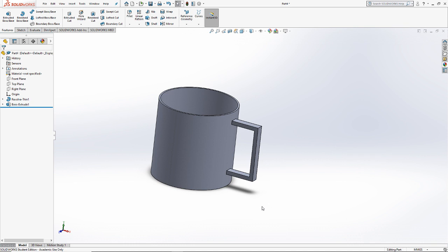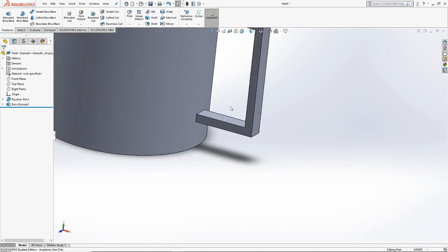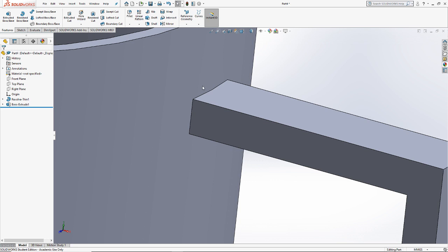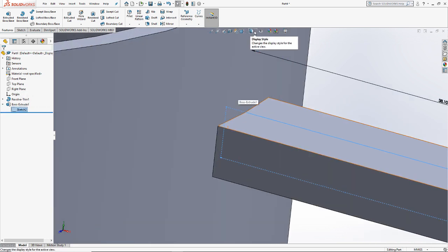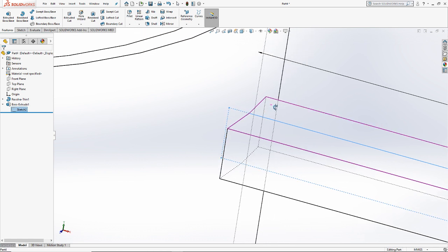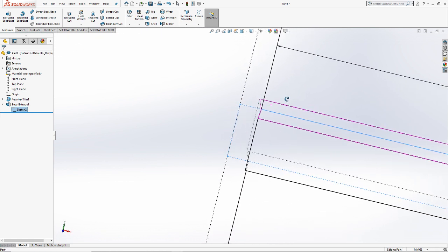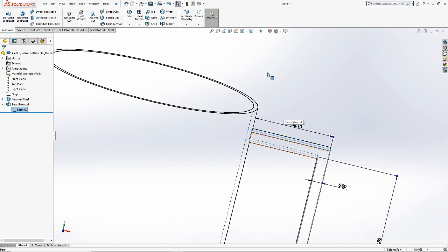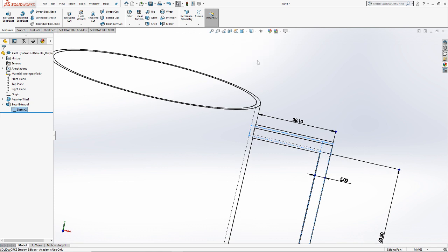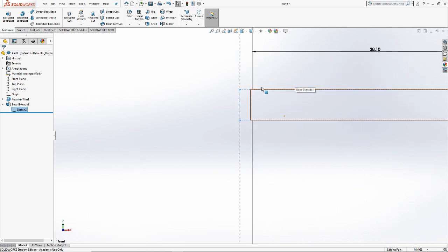There are more ways. You'll notice that when I drew my sketch I drew it such that the inside edge of the handle was actually on the inside surface of the cup. Why is that important to the way that we did this just now? So it goes to the edge. Exactly right. If I had started from the edge and then extruded out, the only part of the handle that would be touching the mug would be the point at the center of that extrusion.